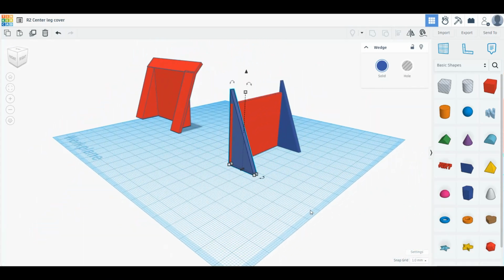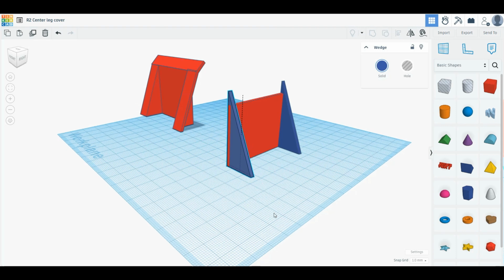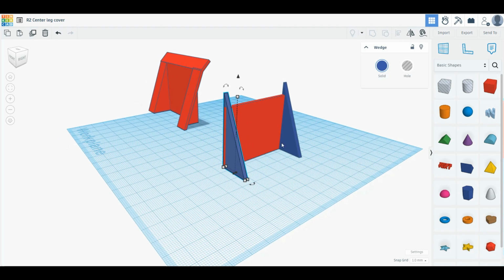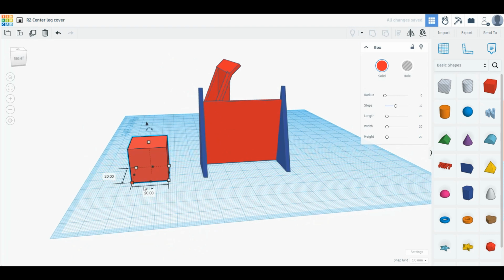Now we've got to provide these two flanges on the side. They are 10 millimeters in size. So we take one of these and convert this into 10. Actually not 10, but let's do 11 millimeters, because a little part of it is going to be extruding into here.